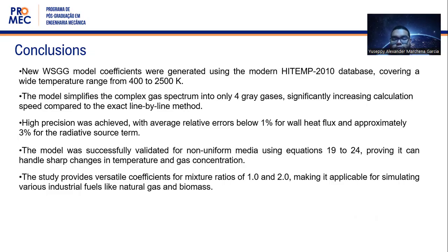More importantly, these correlations can be used directly in the spectral integration of the radiative transfer equation, RTE, enabling the solution of general thermal radiation problems in non-isothermal and non-homogeneous media. The validity of the model was evaluated through several test cases with different temperature and concentration changes, including very strong ones.